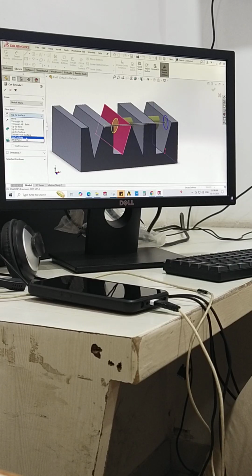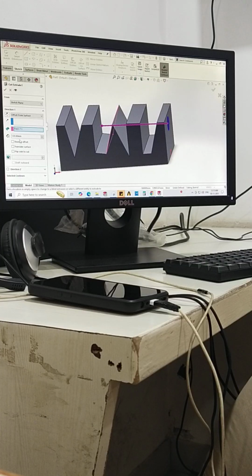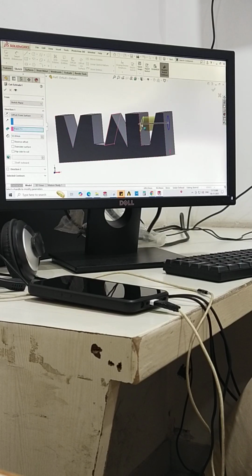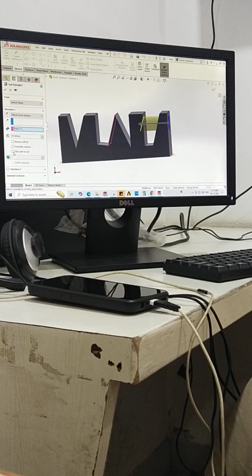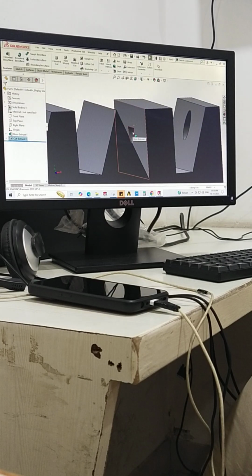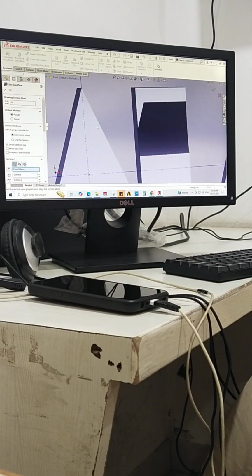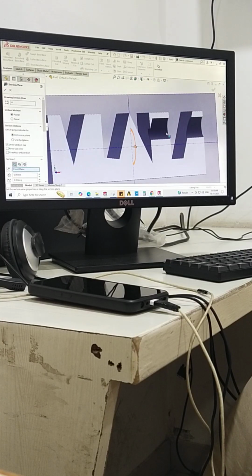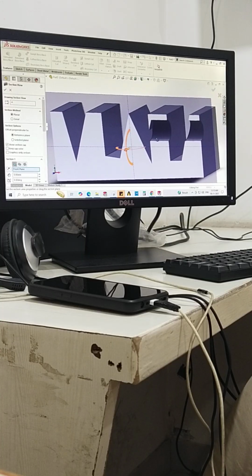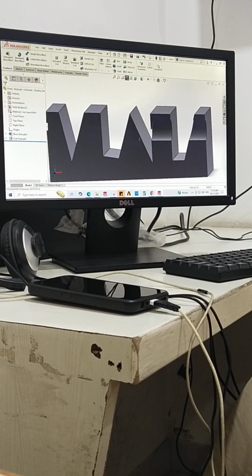Next, up to body is not there in 3D. Offset from surface. Offset from surface means from this surface, you offset 50 mm. Can you see? Parallel, it has been offset and has come here. See here, now I am offsetting 30 mm. So this cut will be there. Can you see? Here, offset. From this surface, offset. Understood? Yes, sir. Any doubt?